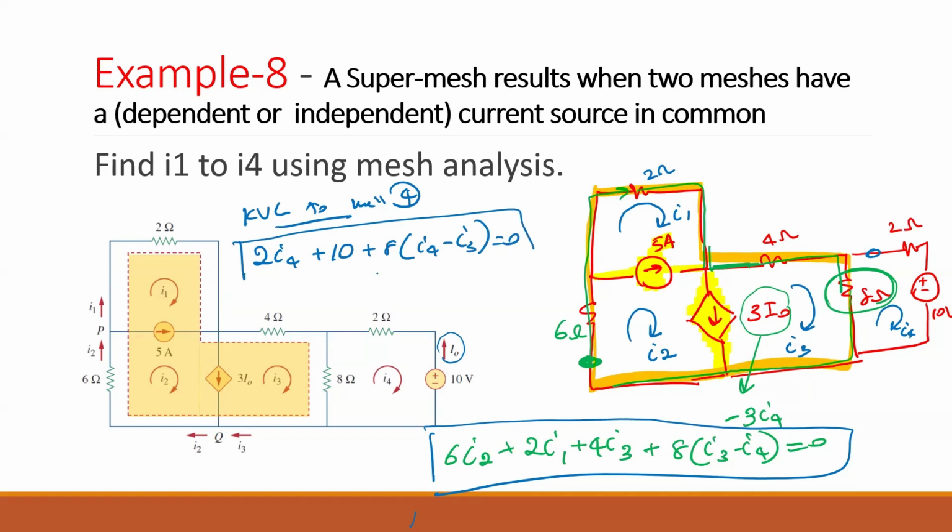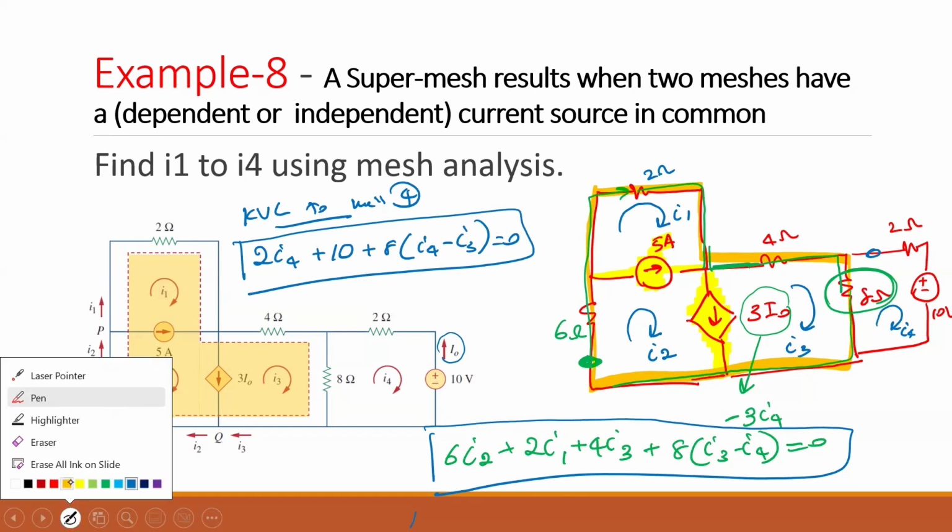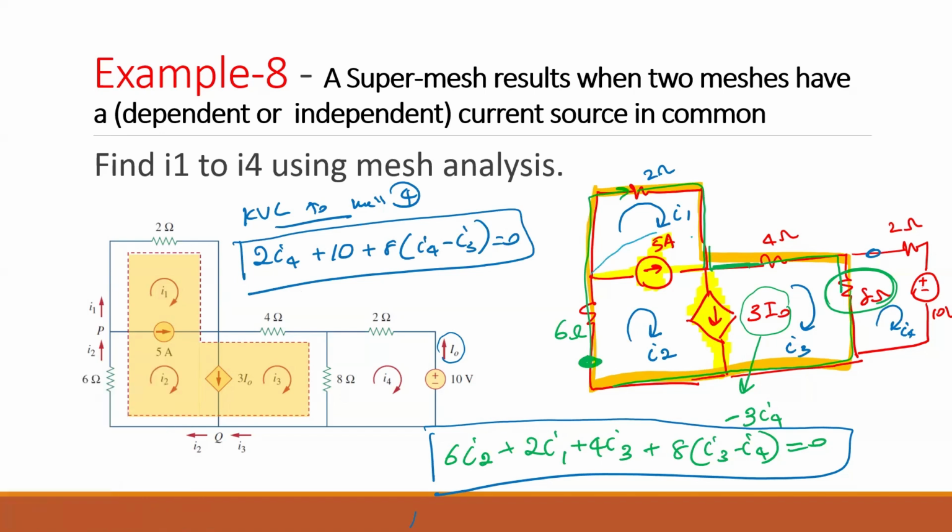Okay. Yep. Now we have 2 equations, but we have I1, I2, I3, I4, 4 unknowns. So you need to now look at your shared current sources. So if you look at this one here, you can say I2 minus I1 is 5 amps. Am I right? Yep. Okay.